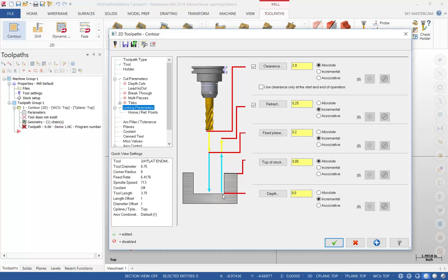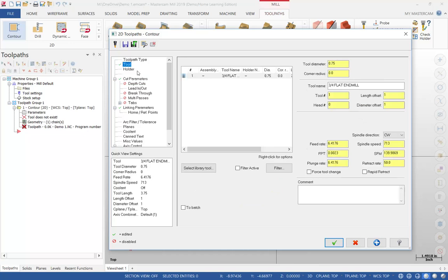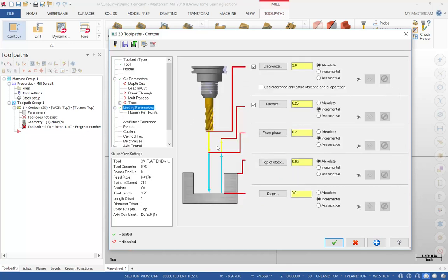And similarly, when you are done with the cutting, you can go back to the feed plane. And when you finish the cutting, that's where the retract is, and you can make it fast going up. So remember the previous setting, the retract was a low number in here. This retract, I increased it just because this portion is not really cutting. I'm going much faster to move to a different distance. So your retract, you can go higher. You can adjust this number as well.